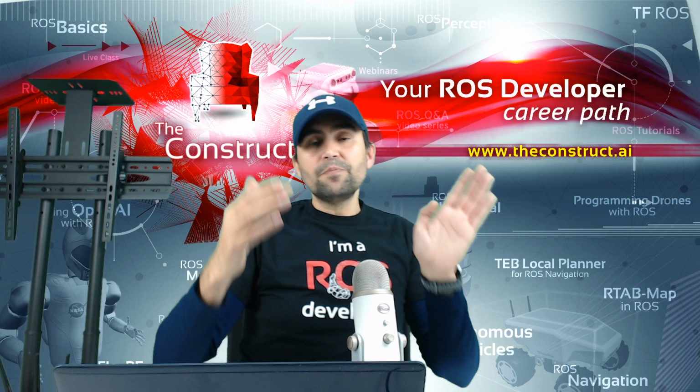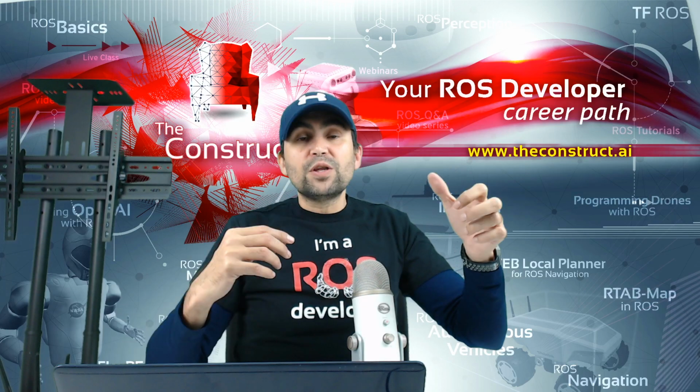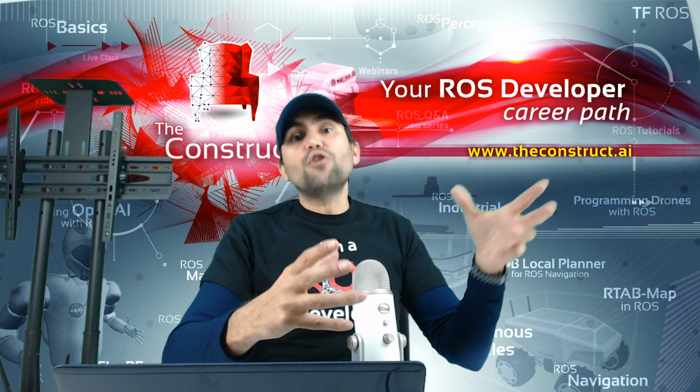But there is another way that is about landmarks. The robot doesn't actually create a grid map. It creates another type of map, a map of landmarks and the references, the distances between the different landmarks and the different orientations. That's another way. Emre says that Cartographer can work in this mode.